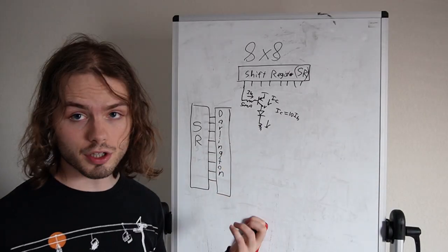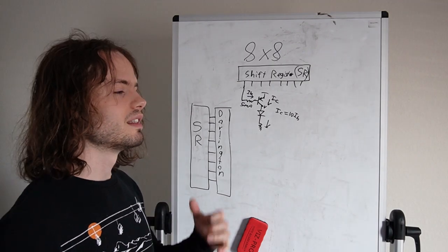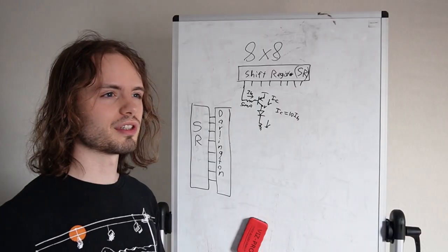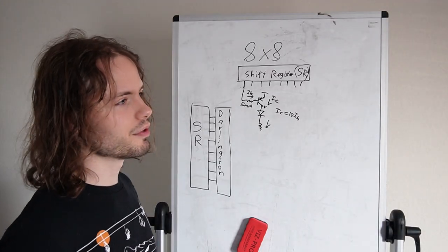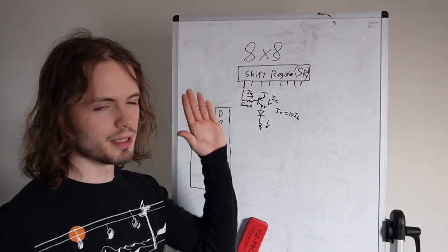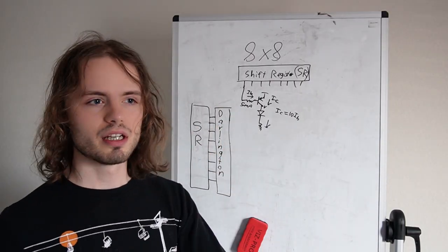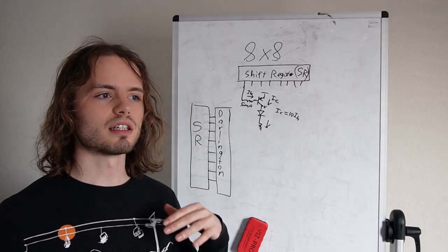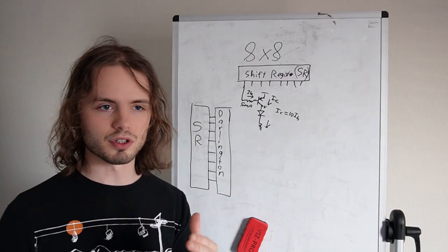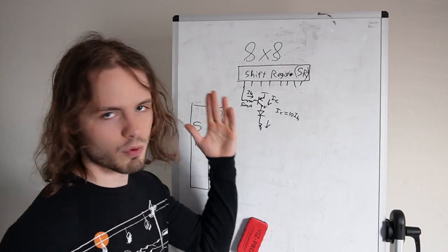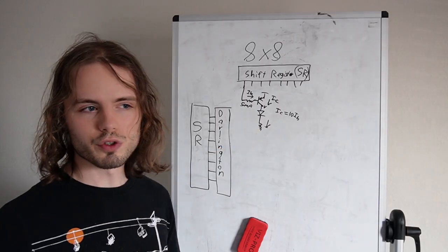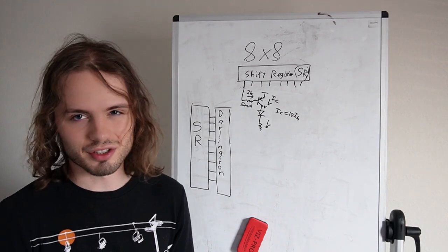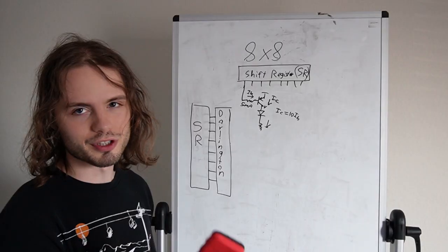And you may ask, why not use a MOSFET? The thing is that we're using pretty low voltages here, about 5 volts, and I'm sure there are some PMOSs that do that, but BJTs also come in through-hole packages, and for MOSFETs, the through-hole packages, the ones with actual leads on them, tend to be more power, so it requires a larger voltage, hence 5 volts won't work. Usually those ones with leads are like 10 volts gate to source, and I didn't want to deal with that. So the BJTs were simpler in this case.